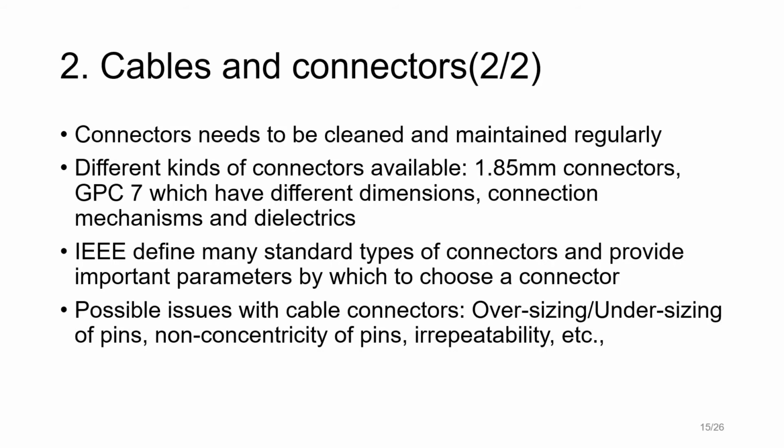The non-concentricity of the pin with respect to the outer shield is another fault which may often be present with the connectors, and no connector provides exactly the same characteristics when connected over multiple attempts. But good connectors though offer, the difference is not too much. So these are things that we can check for when we are trying to test cables and whether they're good.